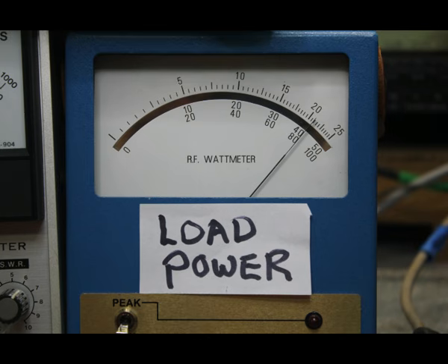And so now we see the power delivered into the load simply by adding a tuner or a matching network, don't care what you call it, at the transmitter end of that 25 feet of cable. Now, restoring the ICOM 746 Pro to 50 watts, of course, we see we deliver 42 watts of power into the load at the far end, even though that cable in between has a 10-to-1 standing wave ratio.